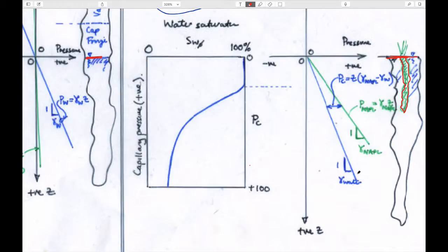And so this equation for this curve is just that the pressure, not capillary pressure, is equal to elevation times unit weight of water. There's a negative sign in there depending on your sign convention, but we're not using that same sign convention. In fluids we use a sign convention, Z is positive up, but this is positive downwards. So this would be the pressure you'd feel in the swimming pool, just in the water.